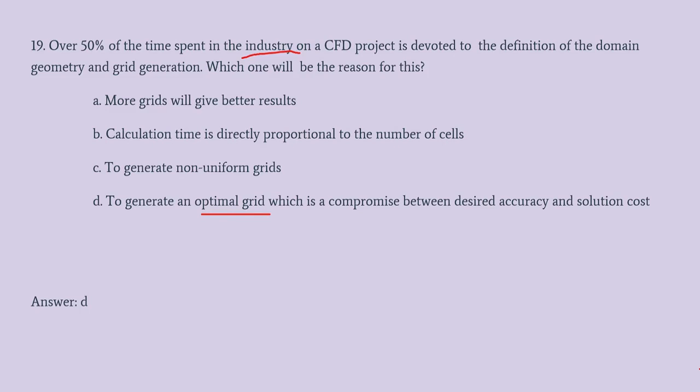So we can fix a value. I told you, CFD is a kind of approximation. We can choose the accuracy. We don't even have to go to the flatter region itself. We can say, okay, this much error is acceptable in my calculation. Suppose 10%, 20%, or 3% error, whatever you can handle. If you have reached that level, then you can fix it. So that's an optimal grid.